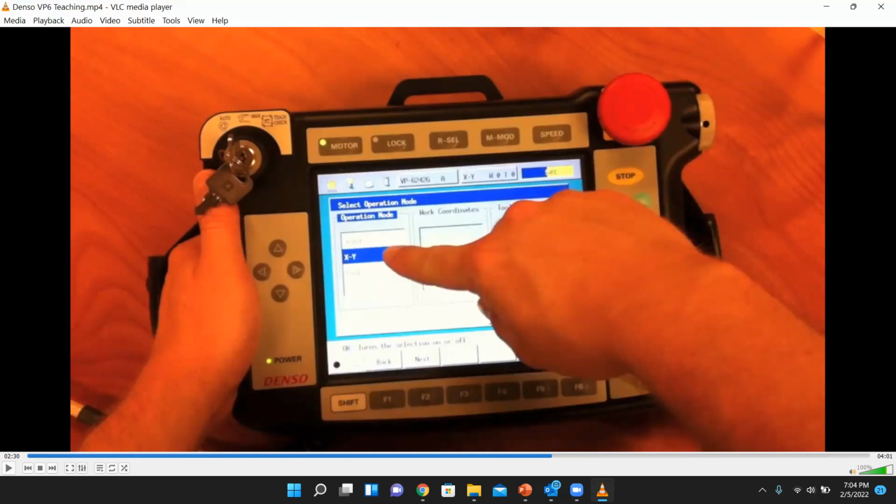Then you enter it into the teach pendant: this is my first point. Then what does the controller do? It will take all the joint positions right now. Every joint has a zero position and an end position, so within that dynamic range, you are at a certain point. The controller will memorize those joint coordinates for all 6 joints, and that is your first point.